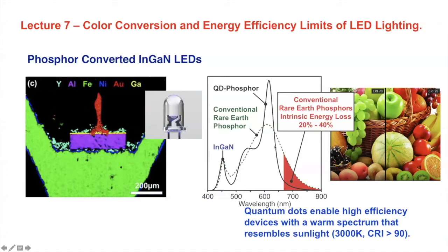So quantum dots are being used in lighting. The world's most energy efficient light bulbs are made with quantum dot phosphors. They have these sharp luminescence bands that are in the red region of the spectrum. And what that does is it allows you to make a warm light source. And this is one of the problems with LED light bulbs. They generally aren't both energy efficient and warm, because it's hard to make red photons in those devices without accidentally making near infrared, unless your red emission source is narrow. And so companies are mixing quantum dots with narrow emission bands to get the color spectrum that they want from their lighting. And as I said, the best, highest performing LED light sources out there right now, based on a single indium gallium nitride color source, have quantum dots in them.